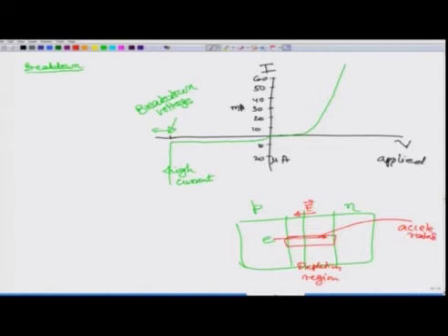Now, if the voltage is high and the depletion region is wide, then it can get large velocities, and if the velocity is large, then that can be sufficient to create new hole-electron pairs. This highly energetic electron can collide with an atom and break the bond there, and therefore it can create new carriers, and that is how this current can increase very high, and that is known as breakdown.